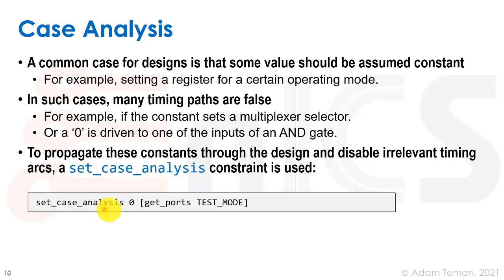And then each of them is going to have the proper case analysis that's going to make sure that we're not checking timing on the paths that are never going to be operated at that speed and show us all kinds of negative slack. Or alternatively, go and try to optimize away really hard to meet timing paths that are irrelevant. So that's what set case analysis is used for. Okay, and I'll talk about MMC in a second, and if I don't remember to relate to this point, then I'll discuss when we use set case analysis in the MMC.